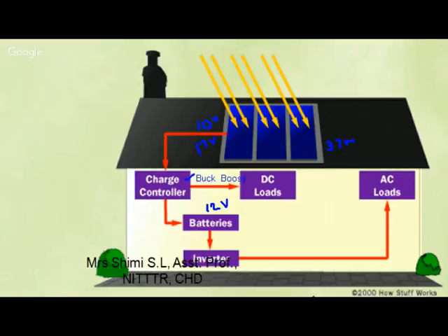Heating purpose. For induction heating or something, you're saying, DC with DC. Mostly when you want to connect it to a grid. Grid voltage will be high, it is not 12 or 24 volts. There you will have an inverter and you will be further giving it. We want the maximum power from the PV and you want to give it to the grid. Mostly you go for boost converters there. So depending on the application and the situation, we have to first know which converter to put there. And all these converters are nothing but the charge controller.